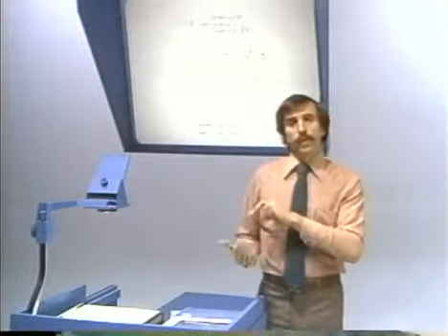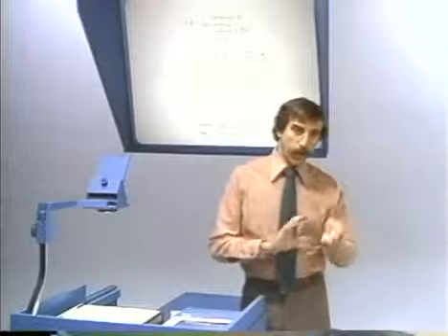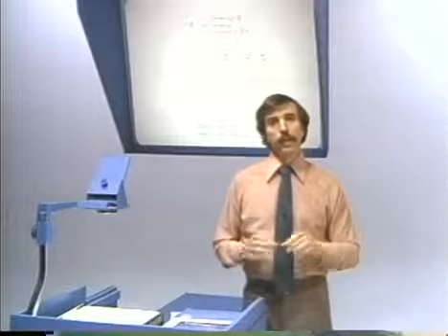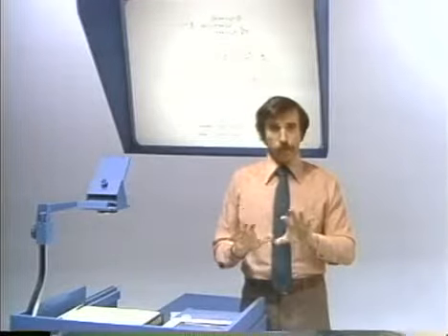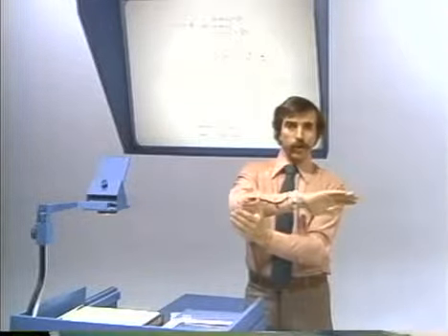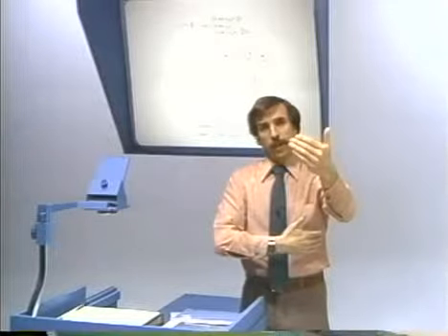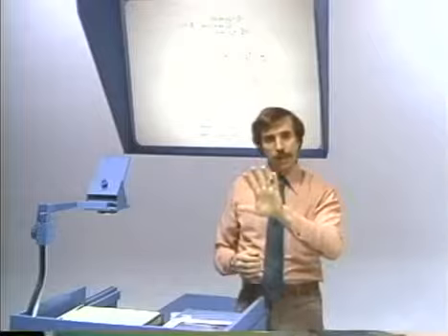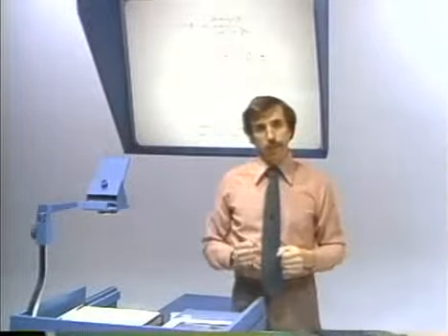Now, when we look at the sinusoid in comparison with the cosine, namely with this particular choice of phase, this has a different symmetry, and that symmetry is referred to as odd. What odd symmetry means, graphically, is that when we flip the signal about the origin, the time origin, we also multiply it by a minus sign. So that's, in effect, anti-symmetric. It's not the mirror image, but it's the mirror image flipped over.